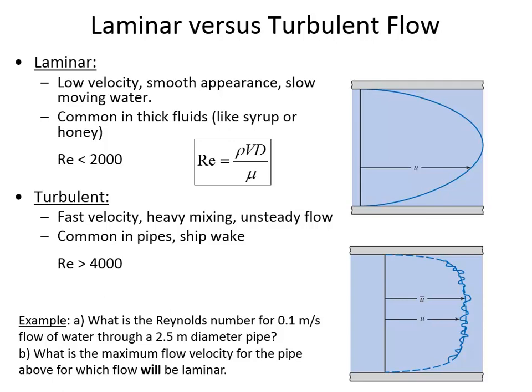It's almost stagnant, yeah. We have a device in the lab that allows us to see laminar flow. It's a translucent pipe made out of acrylic, and it's a very small diameter. And you'll notice that for Reynolds number, if the diameter decreases, then the Reynolds number decreases. So it's a small pipe, and that helps us find the conditions where flow is laminar, and we can observe how laminar looks when it's flowing.